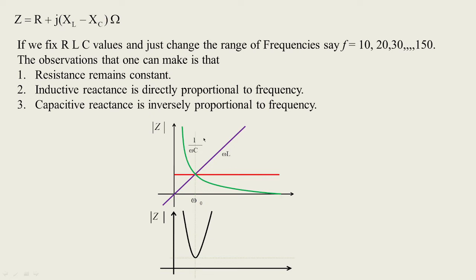You can see that the impedance, when taken in terms of capacitive reactance, gets decreased. In many textbooks or literatures, you can see this is how the impedance graphs look. When the resonance occurs, the total impedance of the circuit is observed to be like this. It is decreasing at one point, and from another point it is increasing.